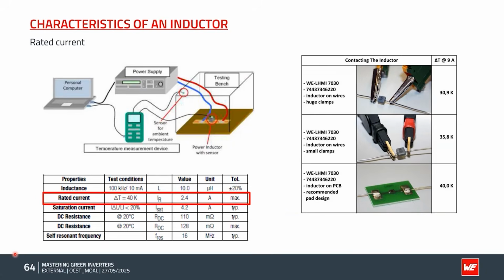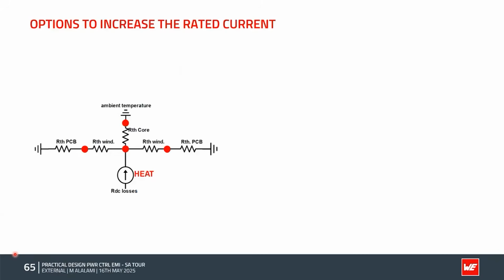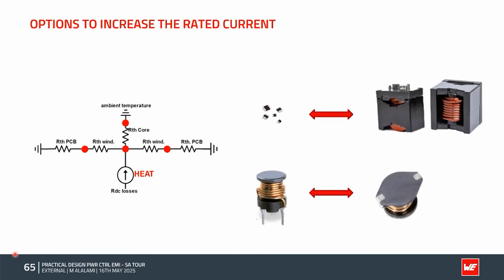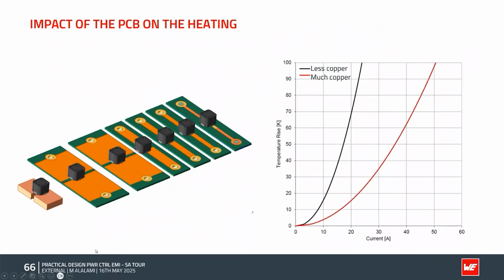And that's where maybe a few slides further down, Andreas, we can also show you what we have decided to do from a Würth point of view, which is to test this behavior using a standard, which is IEC 62024-2. It's an IEC standard that defines specifically how you actually perform the testing on an inductor, including down to the actual PCB itself.